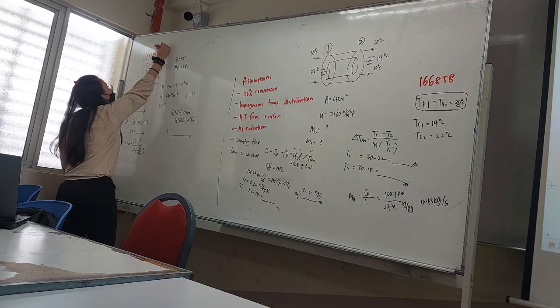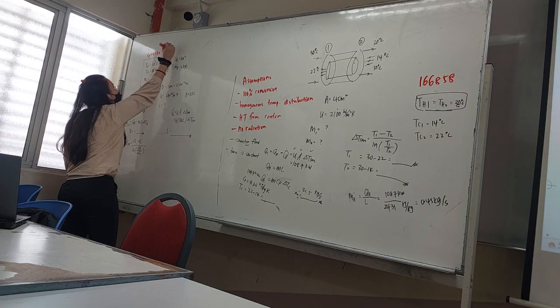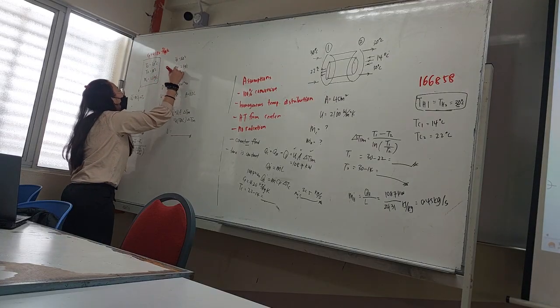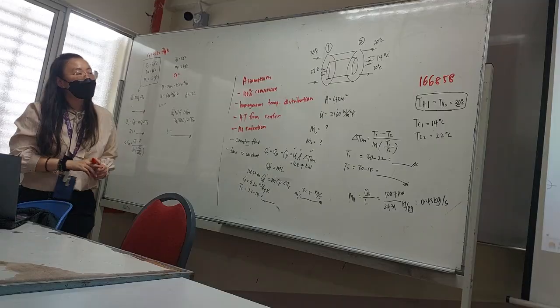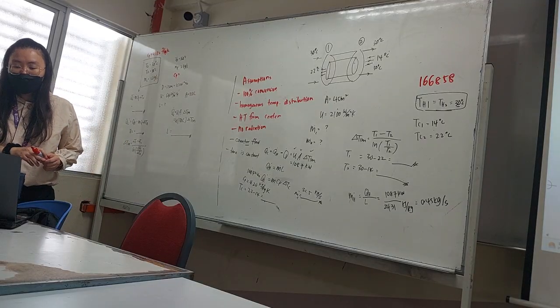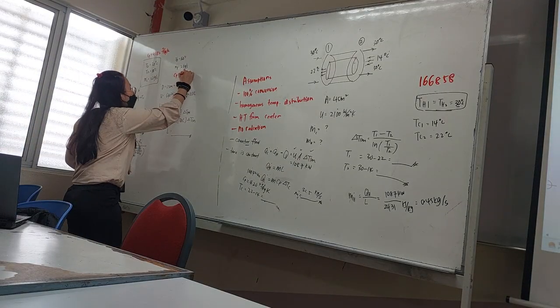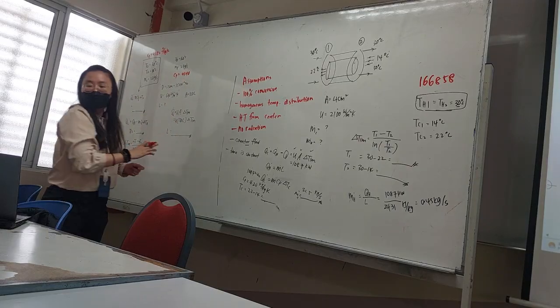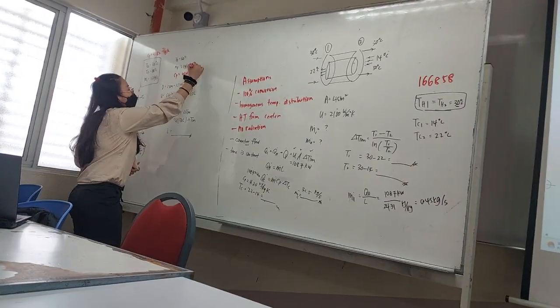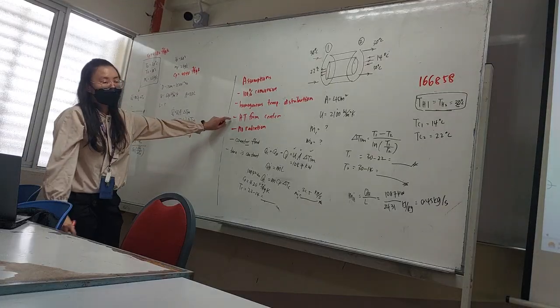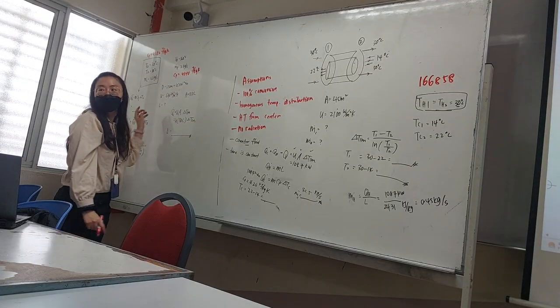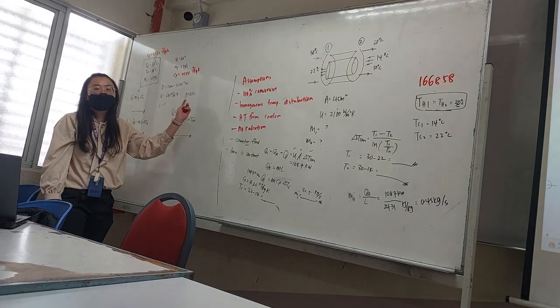Okay, so joule per kg Kelvin. So CP value for geothermal water, because there is no geothermal water in the table, so we assume this is water, so it's 4340 joule per kg Kelvin. Do not forget your assumptions. I'm lazy to copy again, so it's the same assumptions.